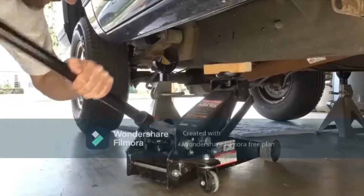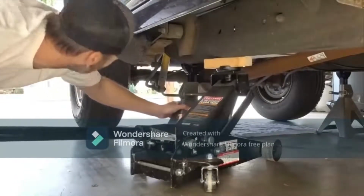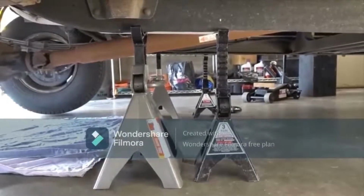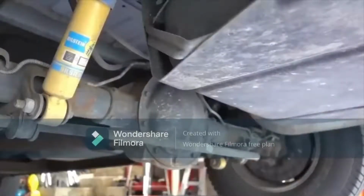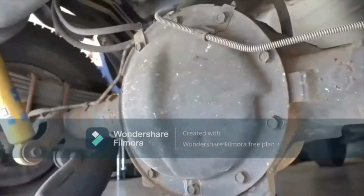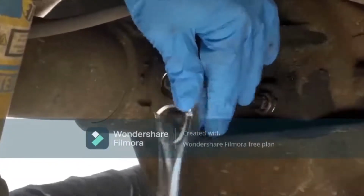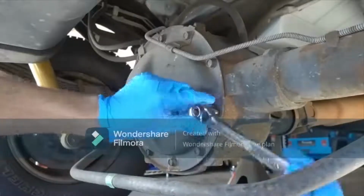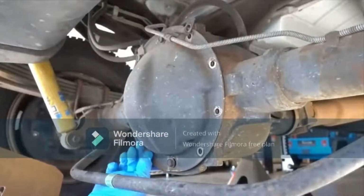These are the general procedures, as the LSD for each model can be different. First, jack up the car to give enough space to work under the vehicle. This will help widen the gap between the fuel tank and differential. Use two sizes of ratchet, first to loosen the bolt for the fill plug hole. Next, to loosen or remove the bolts of the cover or drainage hole. In this case, one bolt on top is left to hold the cover while draining the LSD fluid.